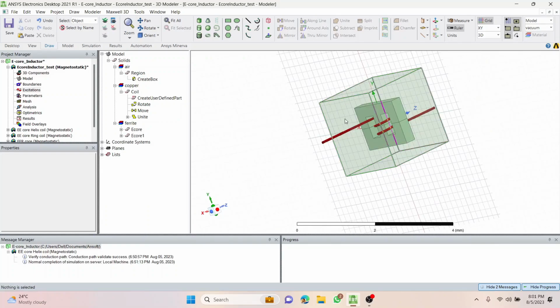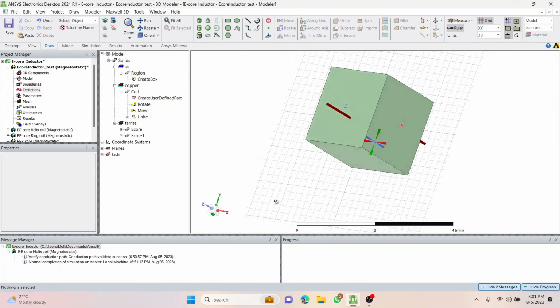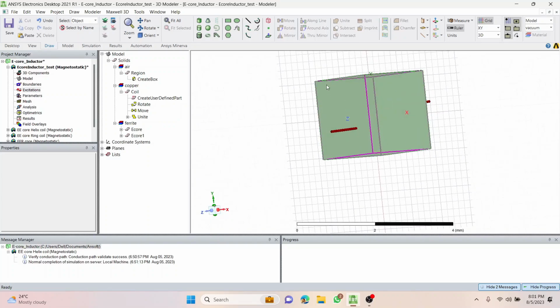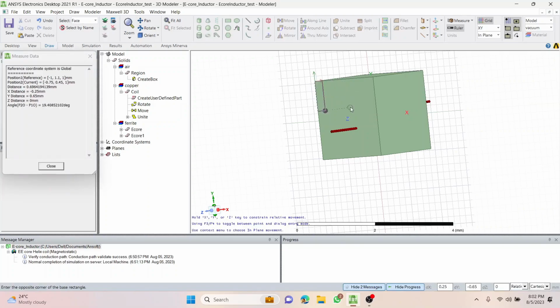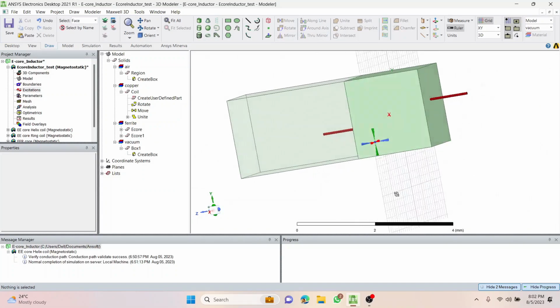First, let's just change the transparency again, make it opaque so that it will be easier for us. Now what we'll do is, this must be exactly equal to the region, right, the boundary. Now for that I will see which plane we are working on. So I will need to work on this section, this face right over here. I guess this is XY plane and our grid is in XY, so perfect to go. I will select cuboid here, just detect the corner, draw the rectangle and cover the whole extension by coming in this direction. Perfect. The coverage is there.